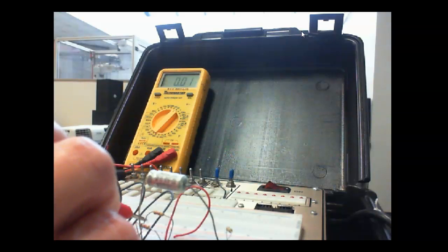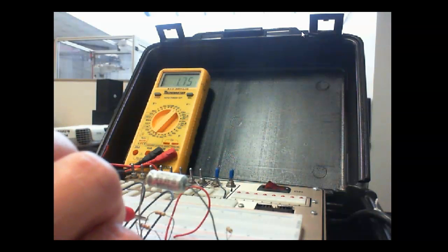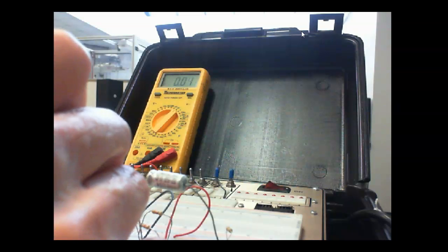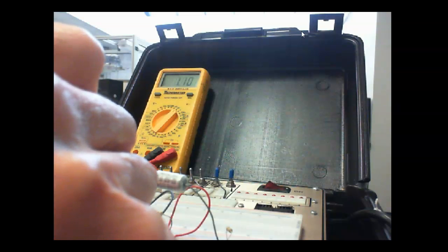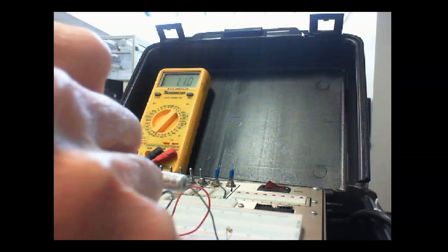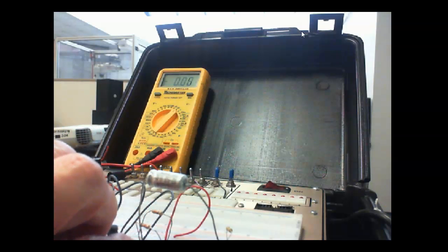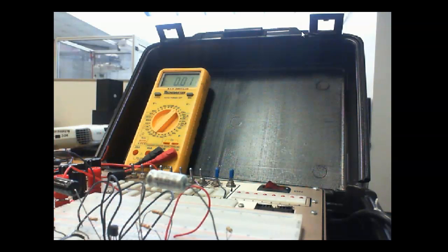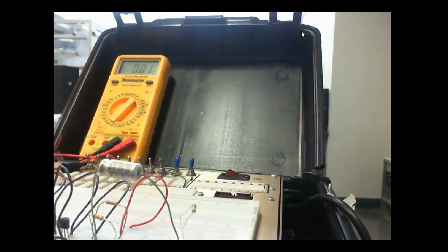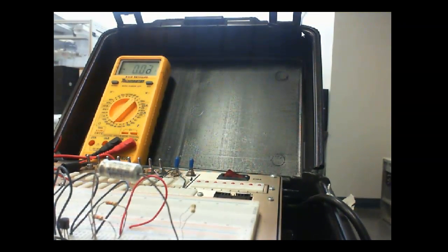So here's the scope. This is C2 open. Let's measure our bias voltages. Here's my base voltage, sitting at 1.75 volts. Here's my emitter voltage, 1.1, I think it's 1.05 volts. Are we okay? Okay, now it's back to normal. I'm going to open up the load. Gain goes up. I'm going to measure my bias. What do you think my bias is going to do?